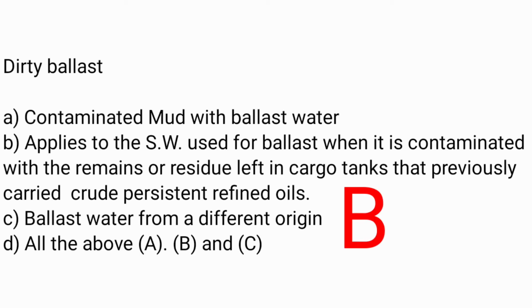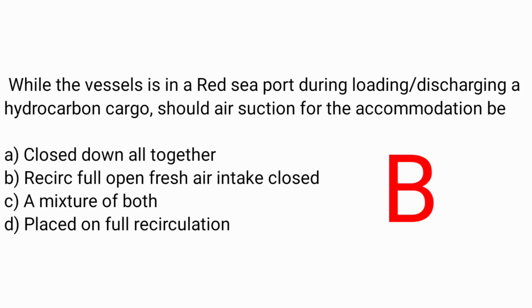Dirty ballast. Answer B, applies to the seawater used for ballast when it is contaminated with the remains and residue left in cargo tanks that previously carried crude or refined oil. While the vessel is in port during loading or discharge of a hydrocarbon cargo, the air suction for the accommodation should be. Answer B, require full open, fresh air intake closed.